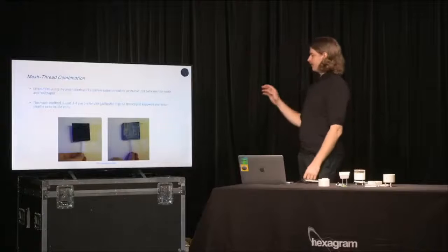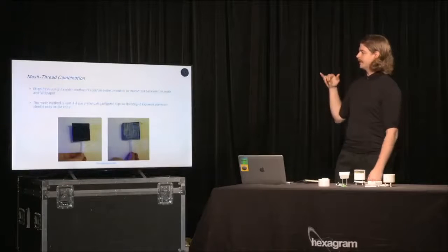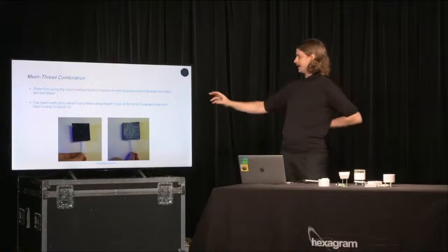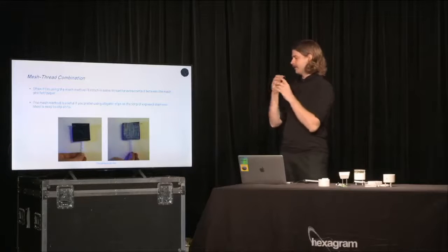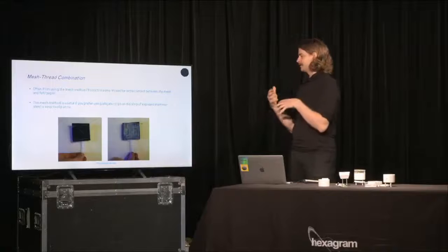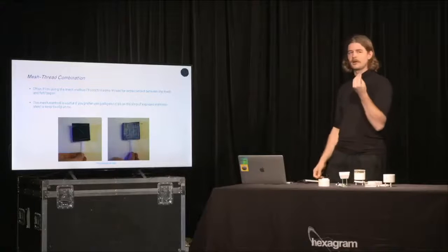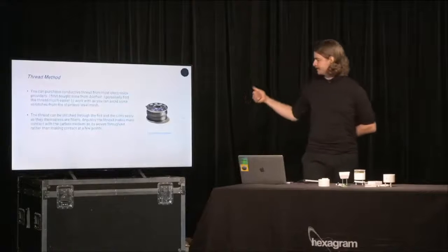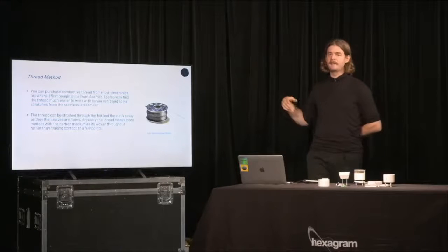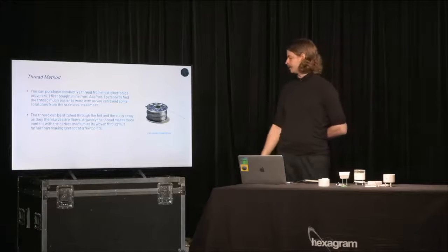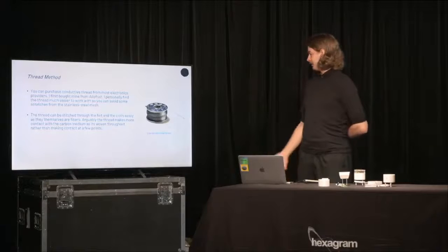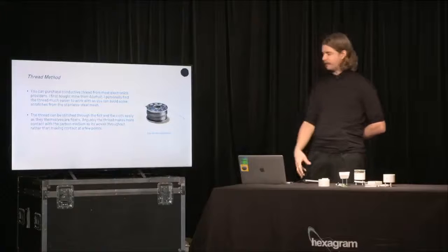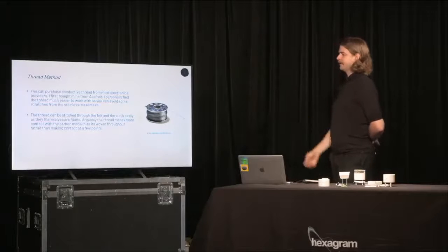You can also use conductive thread, which is the next method, but you can combine them to staple it or sew it into the stainless steel. That way you have a lot more contact. You can buy this stainless steel thread online in places like Adafruit or different suppliers. You can use it in sewing machines too if you want to be really thorough about it. You can do it by hand.